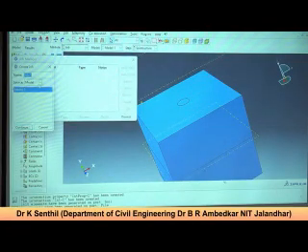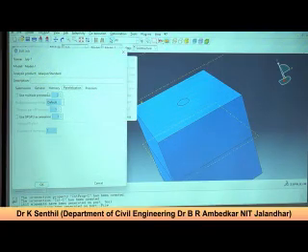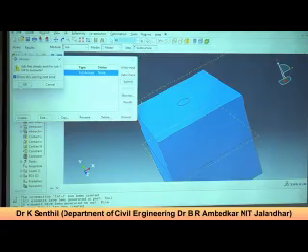So you can create the jobs. If you have already some input files, you can directly feed them and run. Otherwise you can run the model. The model name, let's say job mode, and you try to keep multiple processors. Above 2 is always recommended, otherwise it takes more time. And then the memory and other things, that's fine. So general things. Now let's submit and see the error.